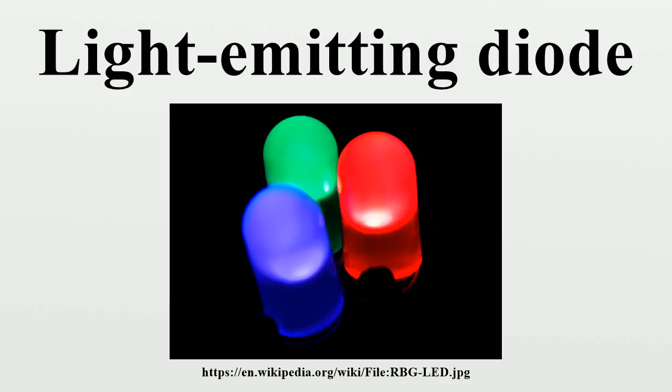The emitted light was detected by a PbS diode some distance away. This signal was fed into an audio amplifier, and played back by a loudspeaker. Intercepting the beam stopped the music. We had a great deal of fun playing with this setup. This setup presaged the use of LEDs for optical communication applications.